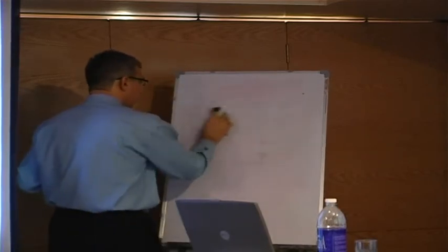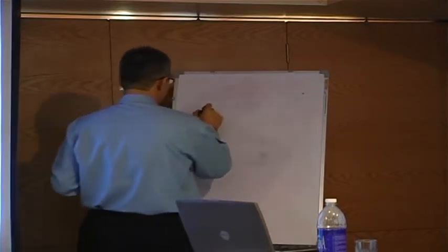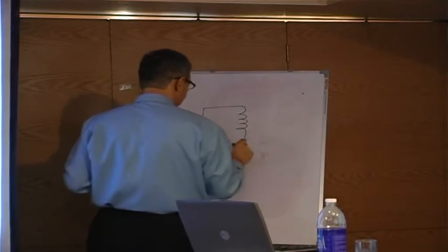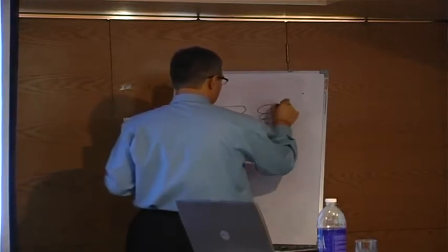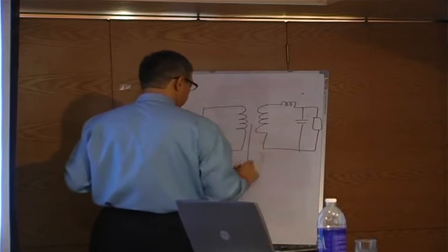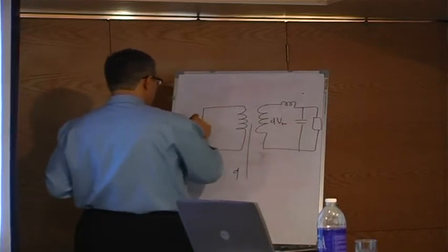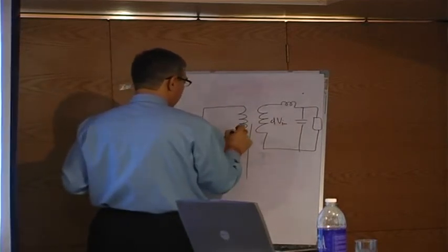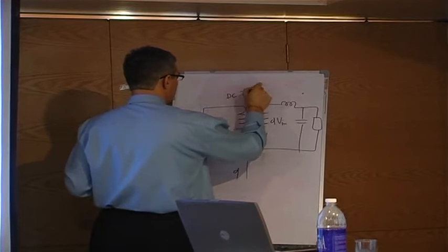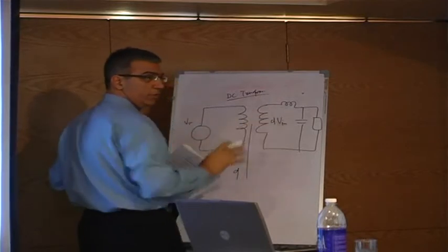Okay. So what it led to was that you can view your inverter as a DC transformer, and then you have an inductor, you have a capacitor, and you have a load. Okay, and this is D, and this is dV in. This is your V in, and this is called a DC transformer. And the D decides the turns ratio of this transformer.